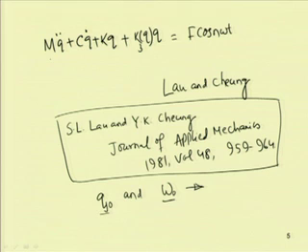In a multi-degree of freedom system, M is the mass matrix, C the damping matrix, K the stiffness matrix, and K 3 will contain the nonlinear terms. It may be cubic nonlinear terms, and F is a force vector. For a single degree of freedom system, M represents the mass, C the damping, K the stiffness, K 3 the nonlinear term, and F the forcing.